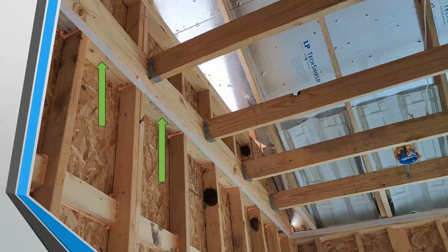A lot of times this blocking is missed where the arrows are showing. So the wall's built up and beyond, and then you've got a ceiling that's in there that's bringing it down. It's leaving kind of a knee wall or a damming over, I think that's a patio in that area. And so you have a misalignment of the air barrier. So you need to create the air barrier at the ceiling plane, which is the junction of unconditioned to conditioned space.